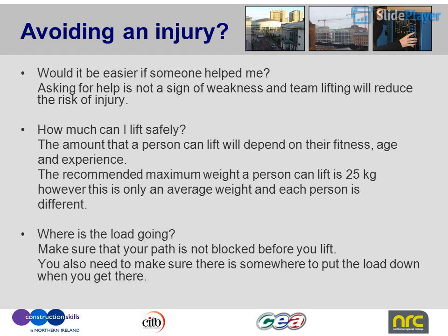Where is the load going? Make sure that your path is not blocked before you lift. You also need to make sure there is somewhere to put the load down when you get there.